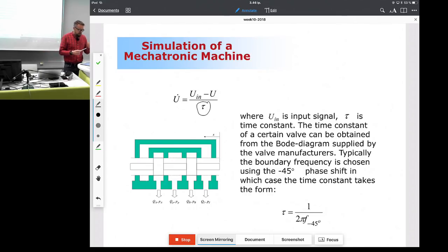It's coming from an experiment where I'm sending a signal to my direction valve, which is a sine function, and I'm just playing with the frequency of this function. In the very beginning the frequency is very low, and the spool is capable of following this signal. But then I started to increase the frequency such that it's becoming like this, you got the idea.